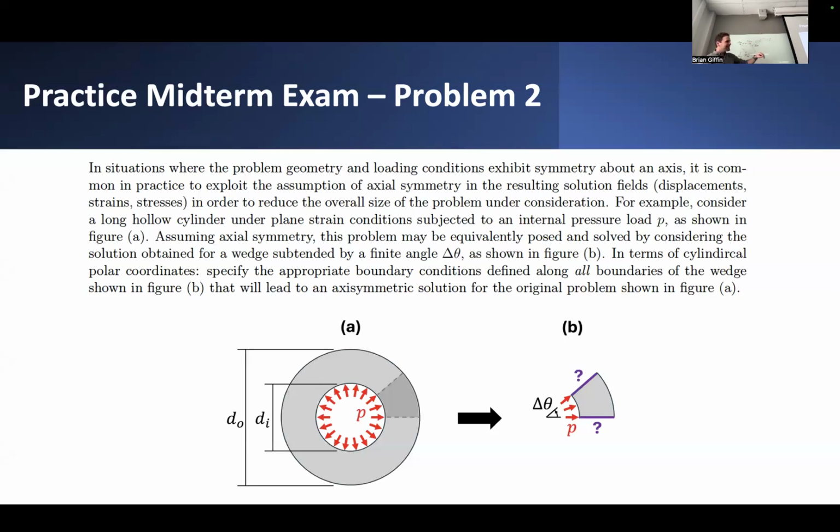In this particular case, on that exterior circular arc, it'll basically say that the radial and tangential shear components of traction on this exterior arc are equal to zero, both of them. So we're not applying any kind of shear force. We're not applying any kind of radial force. All right, so sigma RR and sigma R theta have to be equal to zero along this arc. That's our first set of boundary conditions, traction boundary conditions on this exterior segment.